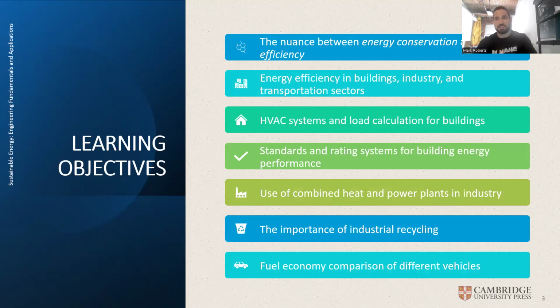An energy efficiency thing could be, with HVAC systems and cooling systems, the temperature where you're rejecting the heat, which is the outside. The lower that temperature is, the more efficient your HVAC system is going to be. So for example, if you live in a hot climate area, if you have an HVAC system that can reject the heat underground where the temperature is much cooler, you can improve the efficiency. And what that means is it's going to do the same amount of work for a lower energy cost.